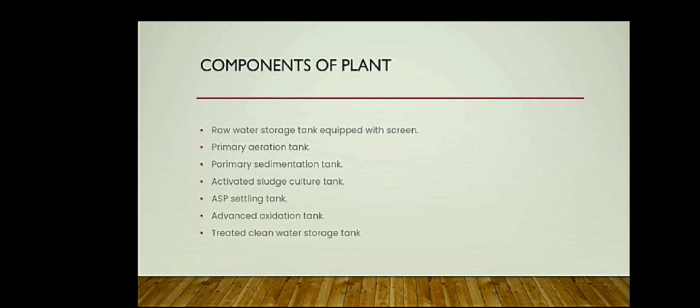What are the components of the plant? Raw water storage tank equipped with screen, primary aeration tank, primary sedimentation tank, activated sludge culture tank, ASP settling tank, advanced oxidation tank, and treated clean water storage tank.